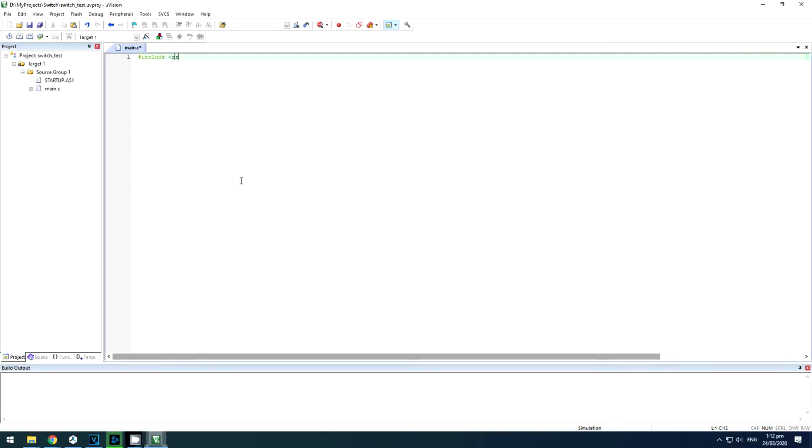Let us code to demonstrate the use of the switch. We use the sbit directive in order to manipulate only a bit in a port. For example, since only one switch is connected, we only like to manipulate P2.0 where the switch is connected. So that the microcontroller knows that it is an input, we write 1 to the port or bit where the switch is connected. In this case, we write 1 to P2.0.